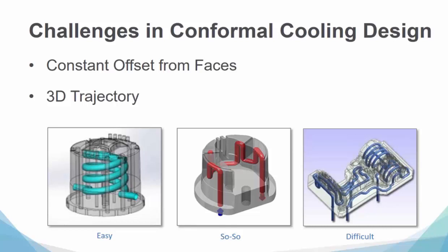That area has been sectioned through different planes, and those planes have been used to guide the direction of that water line as it goes back and forth. Kind of illustrates a bit of a trap too, in that once you get down and into that part, you can make a much longer line than perhaps you intended. And we get back to the idea of uniformly drawing the heat away. Sometimes it's better to break that up as opposed to creating long water lines. So there's some principles already shown here just in these few examples.